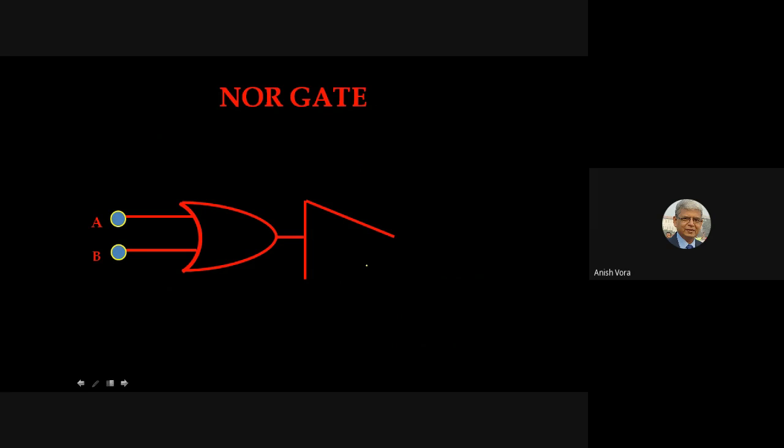And same way we have the NOR gate. So a NOR gate means we put an inversion after the OR gate, then it becomes a NOR gate, right? Very simple. So now we have an OR gate with two inputs A and B. At the output we have again extended our circuitry with the NOT gate. So we have one output, Y1, our intermediate output, and that is A or B. We put the plus sign for the OR gate, A plus B, and then we have the final output Y. So Y is equal to Y1 bar.